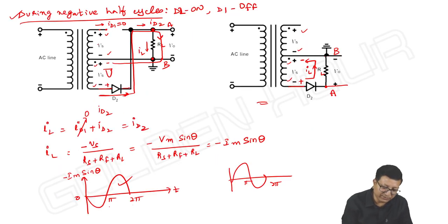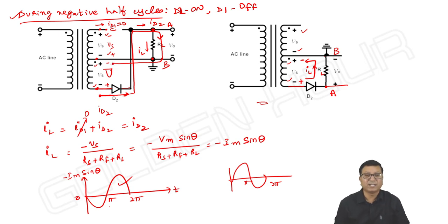Right, again it is Vs between these two, again between these two it is Vs and the current is starting here. Right, with respect to these polarities, if I write this also Vs this way, right, total 2 Vs, the voltage between these two is 2 Vs from bottom to top. And that is multiplied with ID2. Is it possible to write it so? No. If the current starts here and ends here, then I can write 2 Vs into ID2. But ID2 is starting here and ending here. I cannot take 2 Vs into ID2 or IL. Is it not so? Then what should we write? You can't write Vs into IL.